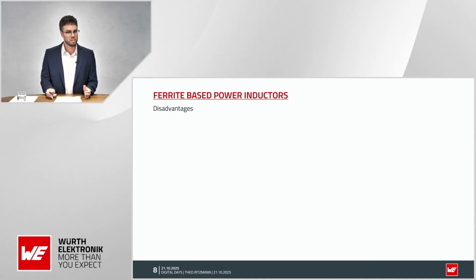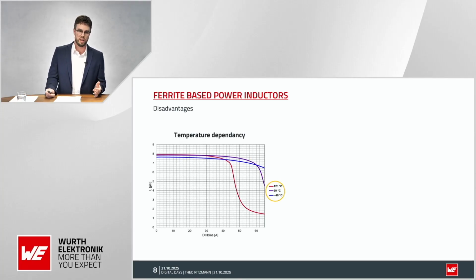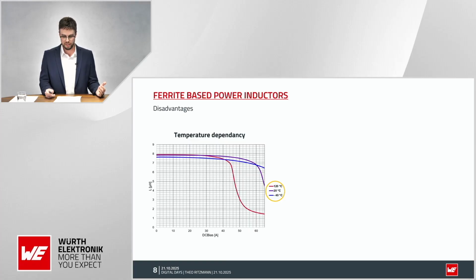But what were the disadvantages of ferrite-based inductors? First of all, ferrite is temperature dependent. This means, as soon as we look at the saturation behavior of ferrite-based inductors, we can see that at higher temperatures, the product starts to saturate earlier.